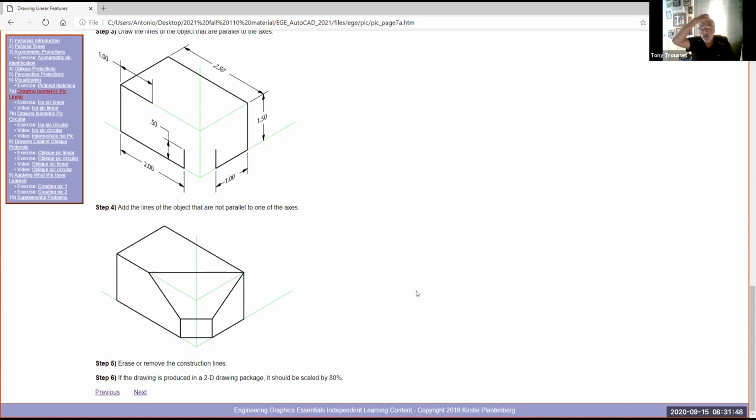I don't know where they get some of this stuff. So it's my job to clarify and tell you, because you really always want to draw something to full scale. The only place you'd scale something down is in paper space, and that's only to fit in your title block. Okay, because when you print the title block, you always put the scale.